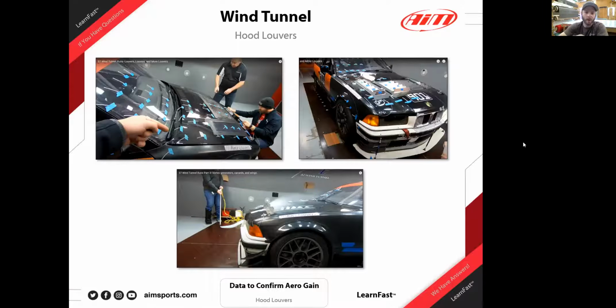Yeah, so on these, I went with a company called Race Louvers. Al Watson started that company. And louvers are pretty cool because it's one of the times where you can really make some good front end downforce while increasing cooling. So it's a little bit of a win-win. It was really interesting. I knew we would see a difference, but just changing some of the angle of the louvers or the opening, or if they're recessed or protruding louvers, I've seen some louvers make over double the downforce and twice the pressure differential on the front and rear of a radiator versus others.